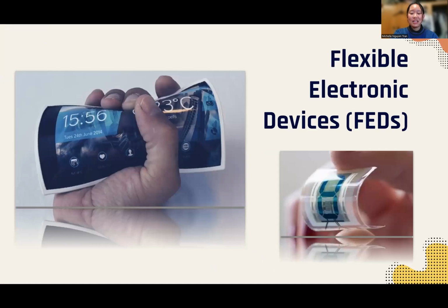Furthermore, the development and encapsulation of organic electronic devices onto flexible polymeric substrates through large-scale and low-cost roll-to-roll manufacturing processes will enable their market implementation in a wide range of areas, including displays, lighting, photovoltaics, radio frequency identification circuitry, and chemical sensors, as well as a whole new generation of modern exotic applications.